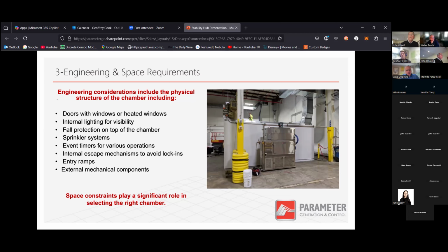Some chambers will just have straight power to the heater, running that heater on all the time, and you might lose a bit of uniformity near your door or window because of the amount of heat they're putting off. We will actually tune our door and window heaters to operate at just 1 degree above the dew point inside the room to only keep the door and window as hot as needed to prevent the condensation from forming, but also retain your uniformity inside your entire internal space.